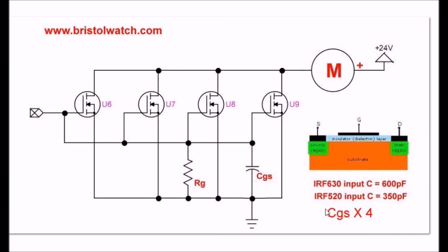Now, when you connect these MOSFETs in parallel, you've also connected this capacitance, this de facto capacitor that exists within these devices. You've connected all of those in parallel. And if you remember your circuit theory, parallel connected capacitors add. Why is this like that? Let's take a look.